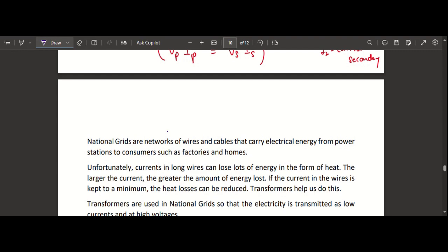current, right? So then when the current is reduced like this, actually current will be reduced to a very small value, 0.00 values or something. So then according to this equation, when current is less, the resistance is still the same, so then it will reduce the energy loss. Okay, right. Okay, so this is the purpose of using the step up transformer.